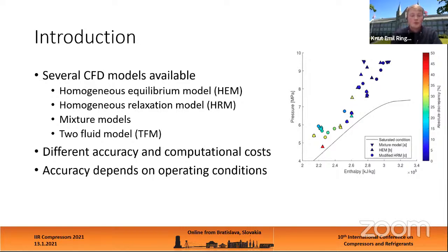Some of the most prominent ones we find in literature are the homogeneous equilibrium model, homogeneous relaxation model, HRM, different types of mixture models, and we recently presented a two-fluid model to try to get a good modeling of the CO2 ejector.